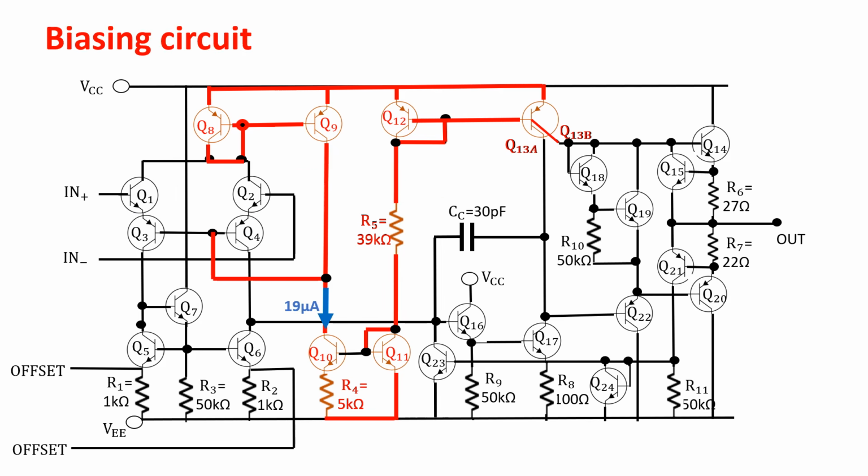Let's see the negative feedback. If for some reason the current in the two branches increases, then the current in Q8 increases, and so also in Q9. But because the current in the Widlar mirror remains constant, the excess of current goes to decrease the base current coming from Q3 and Q4, then decreasing the current in the two branches.